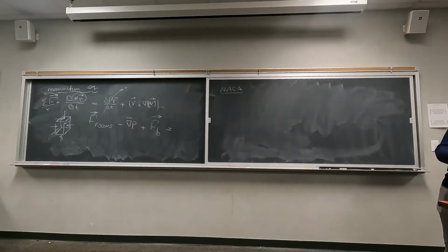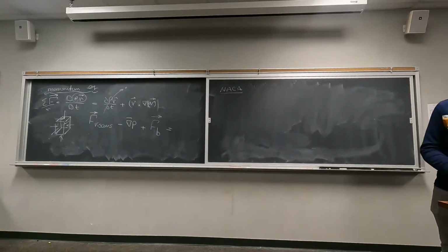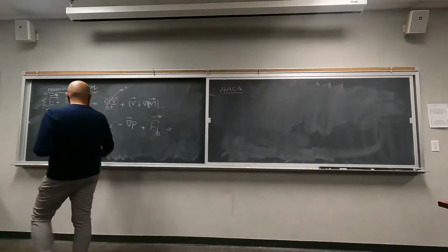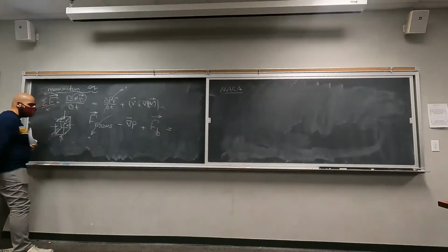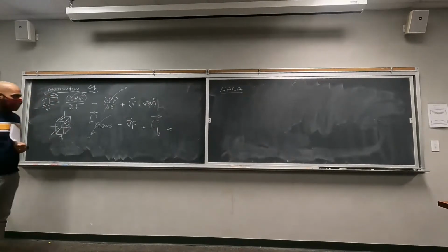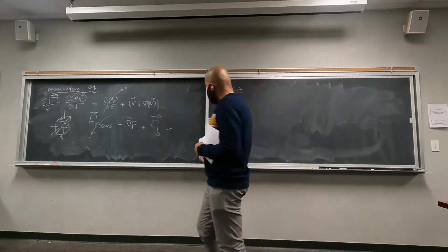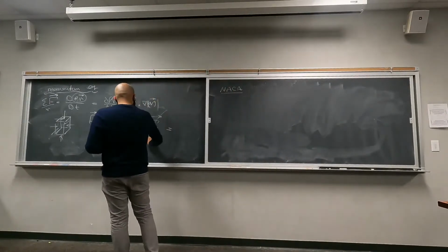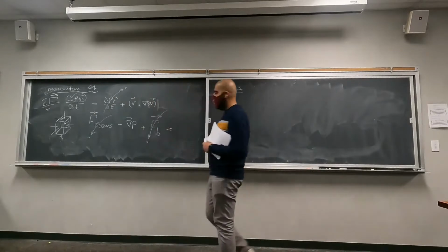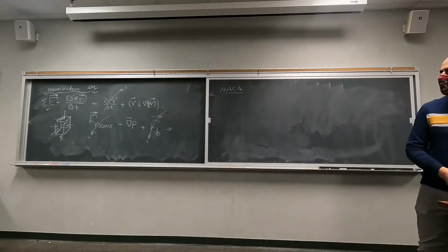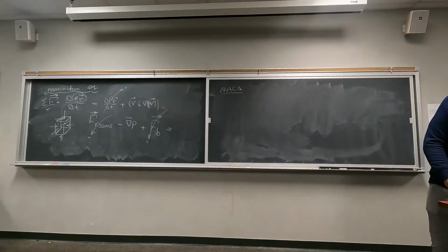They were dealing with very low speed conditions, so they could safely assume that viscosity effects are not there. This part is also zero. And the drag force is essentially going to be much, much higher than the lift inside the wind tunnel. So the weight was also zero. A lot of simplifications until this one.